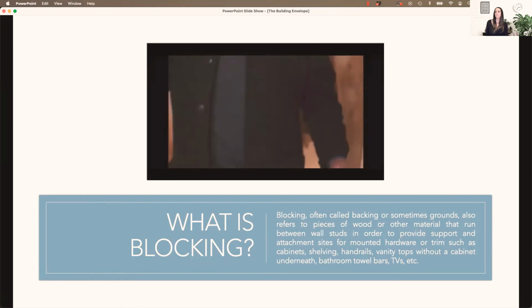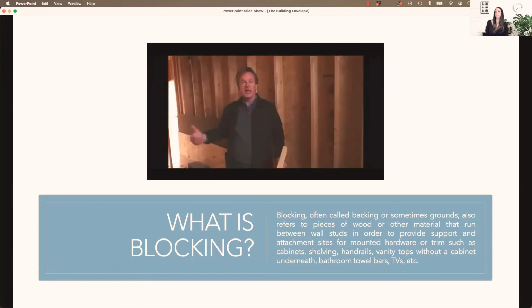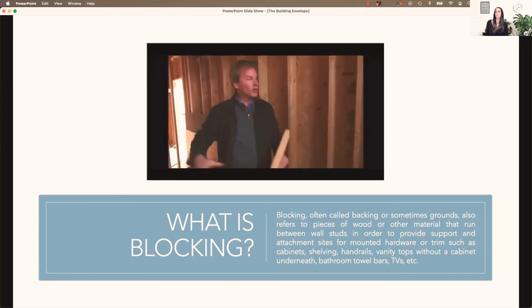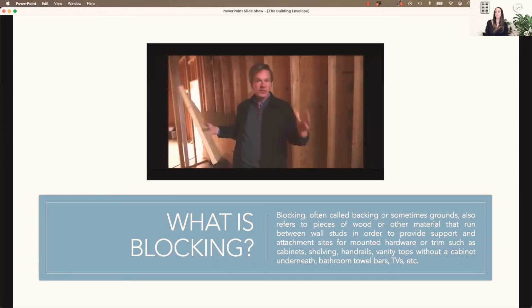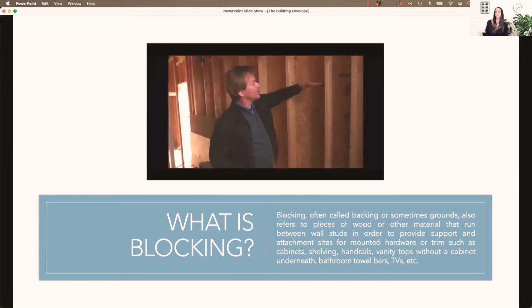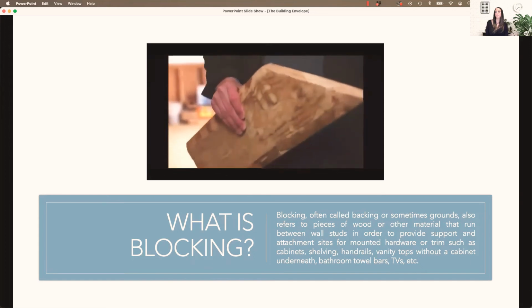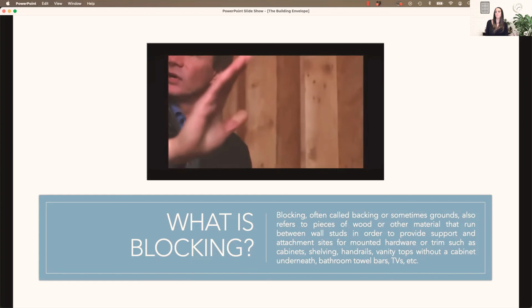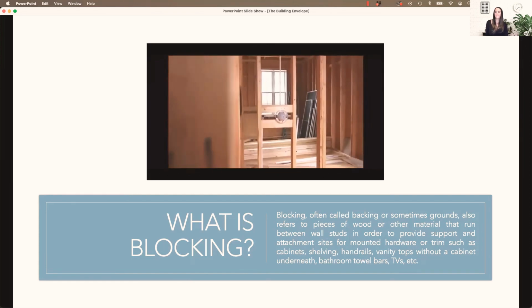Whenever you're thinking about a house and you've got it stripped down to the stud walls like this, and you know you're going to hang a heavy mirror, you know you're going to do cabinets on the wall, or you've got a big piece of art, a piece of sculpture, something that needs support, this is the time to get it built into the stud wall. Then we're going to come back in certain areas with our finished material, our finished skin, if you will, on the inside of the house.